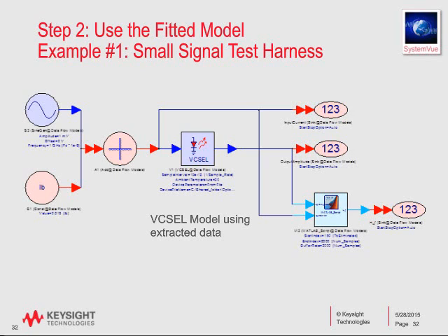And then we're doing a very simple block, actually like a MATLAB block here inside of SystemView, because SystemView supports the ability to use MATLAB code, and then calculate the frequency response, which is the bottom right-hand sink, the 1, 2, 3 in the bottom right-hand corner. So that's giving us a frequency response. So we can use this setup to sweep both time and frequency. So what do the results look like?